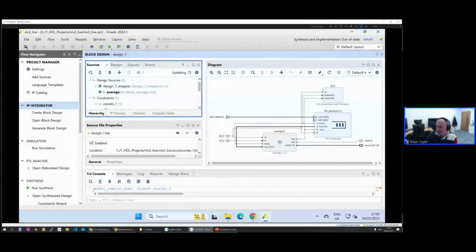So this is a good question. The ILA also includes its logic in the implementation. It's one of the interesting points about implementing ILAs that by putting an ILA in the design, you change the behavior. You can change the implementation, the floor planning, the behavior of the design, such that if you had an issue, you put the ILA in and then it goes away.